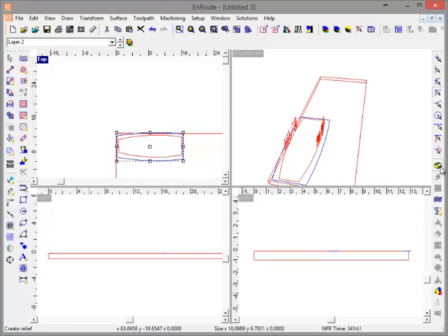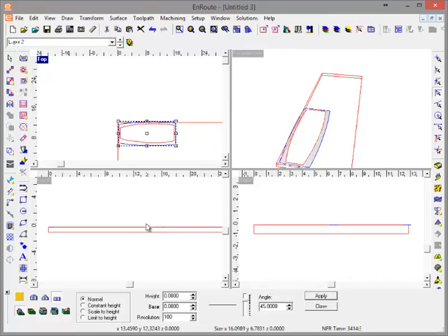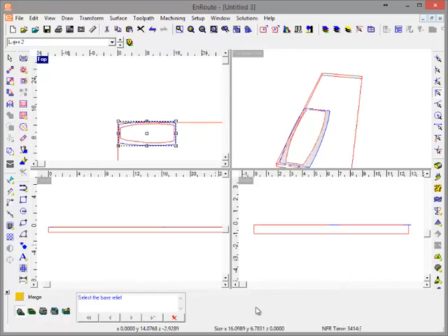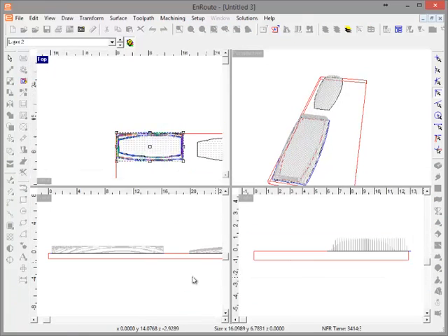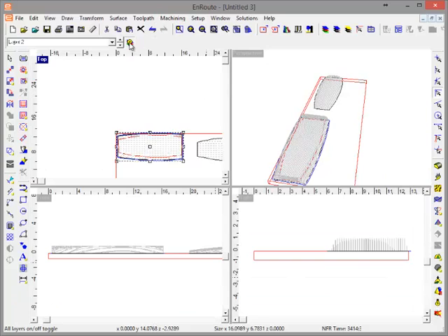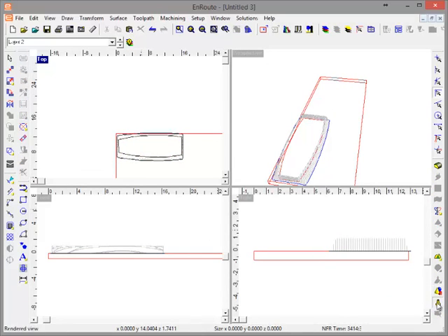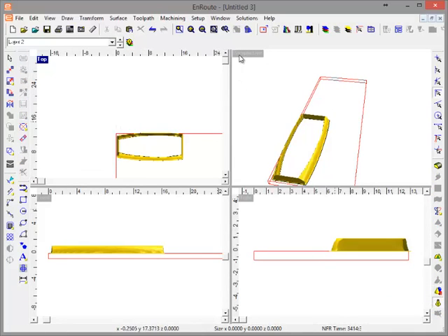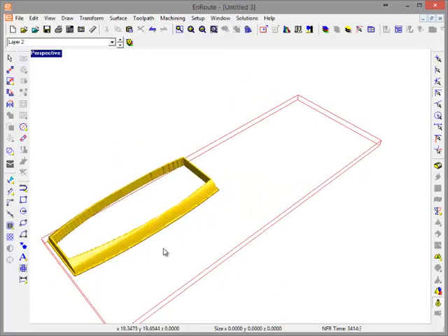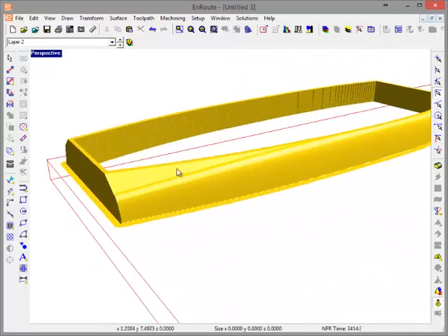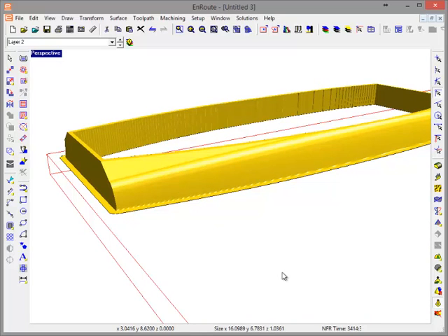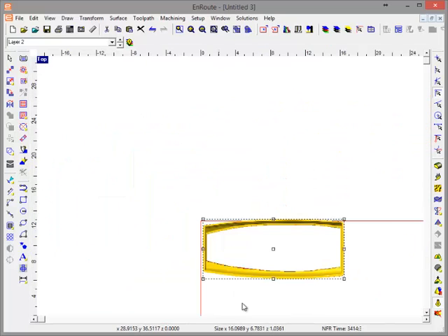Now I'll come here and create my relief once again. Merge reliefs. Select the base relief. Select the relief I want to add to the base relief. Green check mark. Turn off all layers. And finally, after a fair amount of making some errors there as I figured this out, we have a section of the relief, and that section is